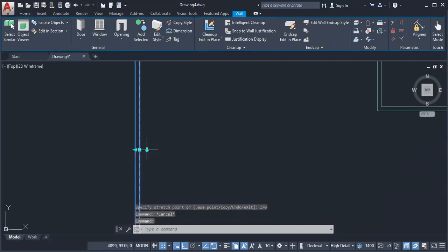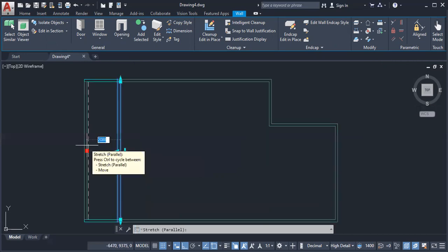Again, I can also move this wall. So I click here and drag, and this wall will extend out somewhat. As I move out, you will notice that blue box, which is indicating the adjustment. You can enter a specific amount that you want to extend this wall by.